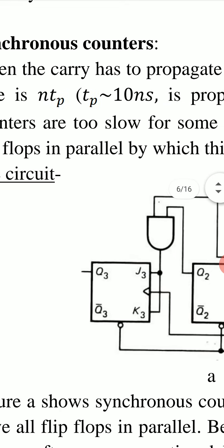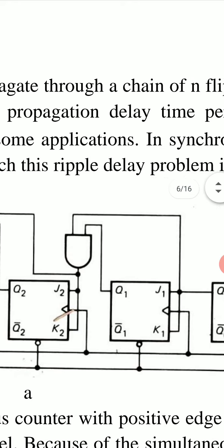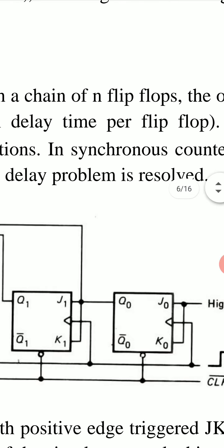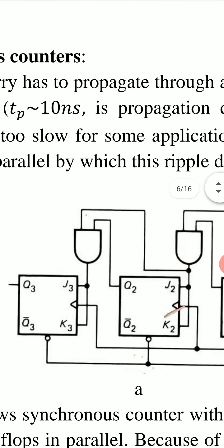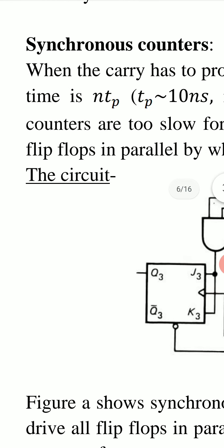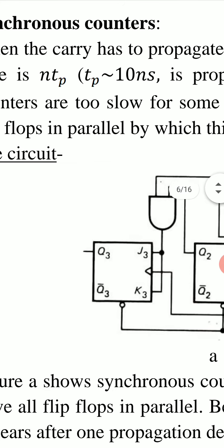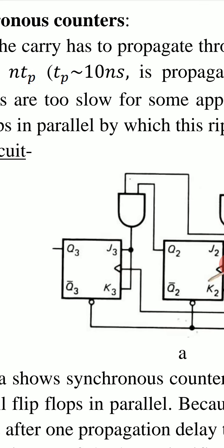When the carry has to propagate through a chain of n flip-flops, the overall propagation delay time is n times TP. TP is of the order of 10 nanoseconds.